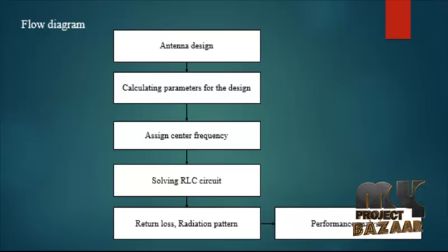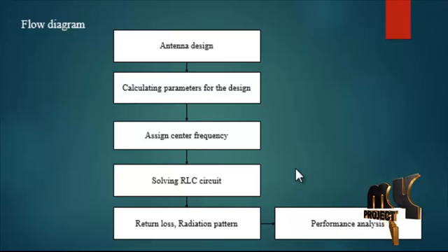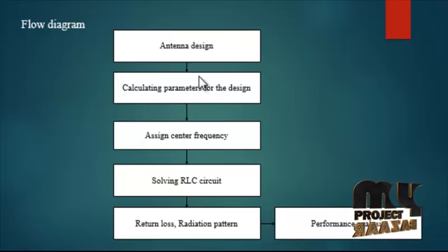Antennas with coaxial probes normal to the body surface will cause inconvenience and discomfort. To solve this issue, the transition of the feeding position to a microstrip line is utilized, which facilitates soldering of the coaxial connector. The upper patch, the microstrip line and the ground plane are etched on a 1 mm thick FR4 substrate.